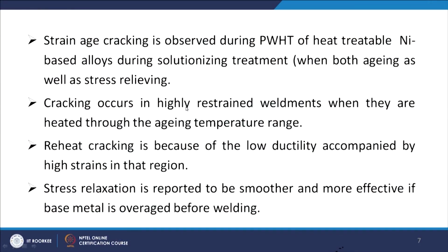Now, if you talk about reheat cracking in the nickel based alloys, it is the result of low ductility in the HAZ accompanied by high strains in that region. In those cases, many a times the practice is that you overage before the welding. That sometimes gives better results.